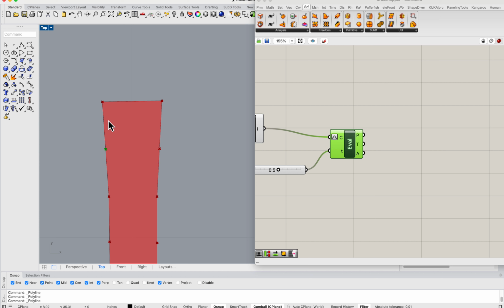So for the zip ties, it depends on the tolerances. You might want to try how big of a gap you need to leave for the material, as well as the hole for the zip tie to pass through. But we can probably do 0.2 inches or something, less than half an inch width for the gap.